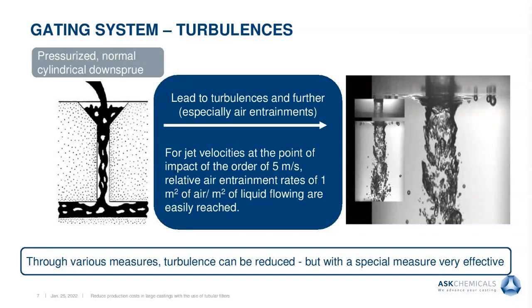Air entrainments. The left-hand picture shows a simple and typical downsprue used to pour castings, and the right-hand picture shows, in my opinion, very impressively what happens during that entrapped air. You can see it here. The air entrainment during mold filling is really a main source of the oxygen that is consumed in reoxidation inclusion formation.